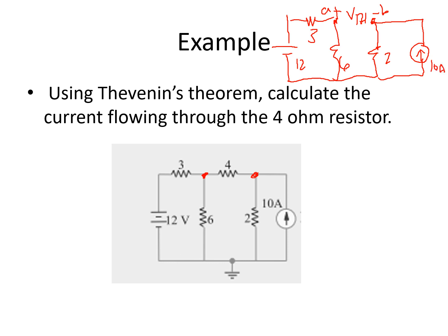So to solve for the voltage across VTH, we need to have our loop here. However, we have to know first the voltage at 6 ohms and the voltage at 2 ohms. No problem with the voltage at 2 ohms. Okay, so how do we solve for the voltage across 2 ohms? As you can see, the current source here passes directly at 2 ohms because this is already an open circuit. So therefore, no current will flow to the other part of the circuit. Therefore, the whole 10 amperes will flow across this 2 ohm resistor.